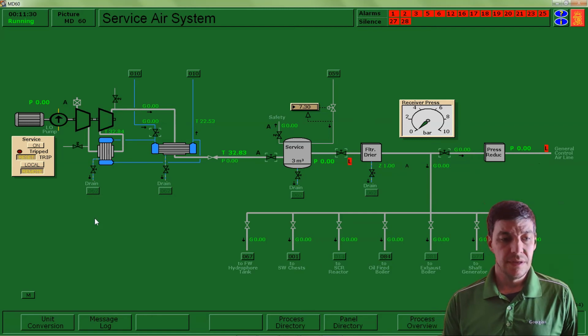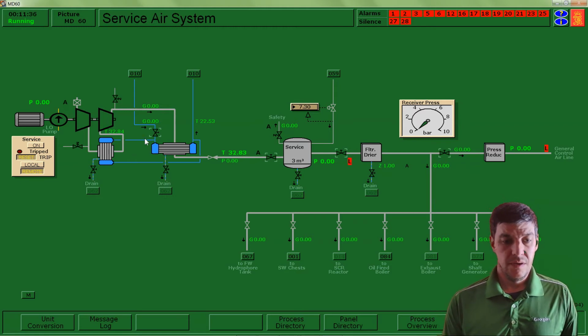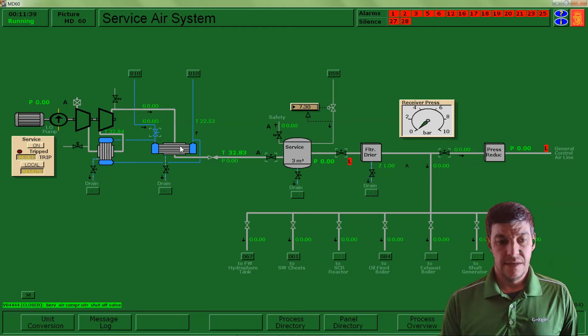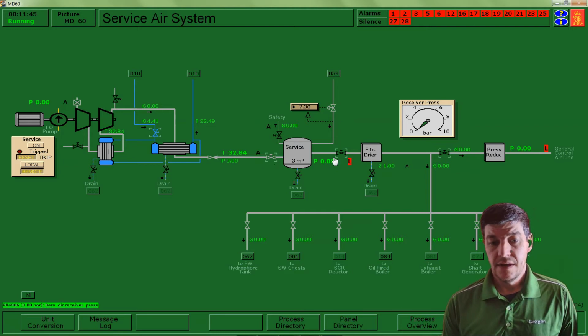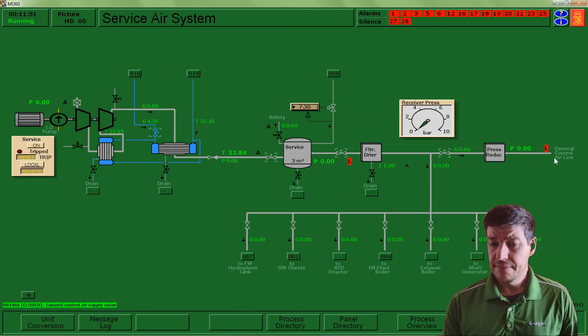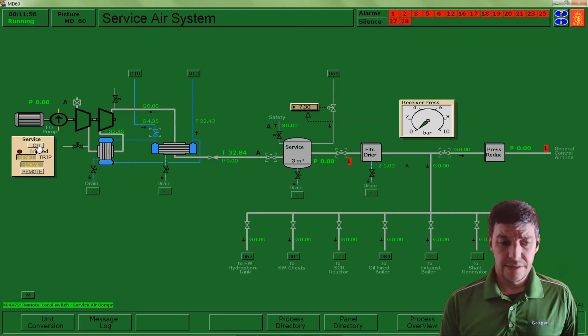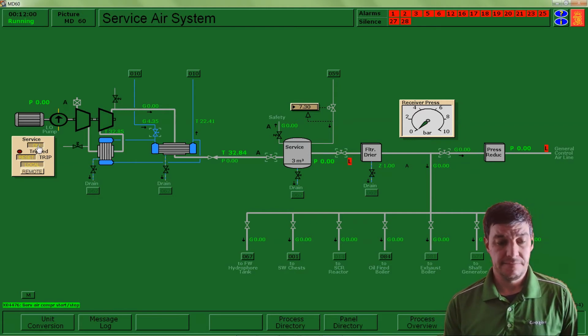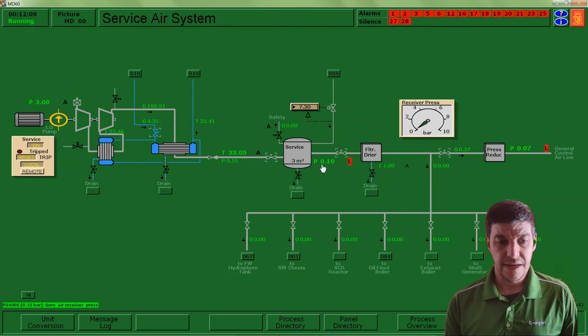So here's what we're going to do. Same process that we did when we looked at our air compressors a couple weeks ago. We'll make sure we have cooling water. We'll make sure that we have a pathway to our receiver. Okay, and in this case, I may continue my pathway along. I'll switch it to local, and I'm going to turn on my air compressor. Okay, I'm going to confirm that pressure is increasing in my receiver and my safety relief valves are not going off.